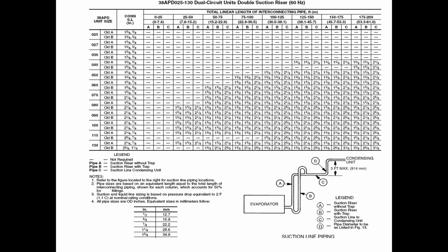We did have a question. Josh asks, say you had to go up to a total of 10 feet. You can do it in 4 different risers. Can you do a speed riser 4 different times? Yeah, you could. It'd be ugly, but you could. Personally, I would look for a different route or see if I couldn't fit a double suction riser in there and get it over and done with. But yeah, you could. That's all we have for questions right now.